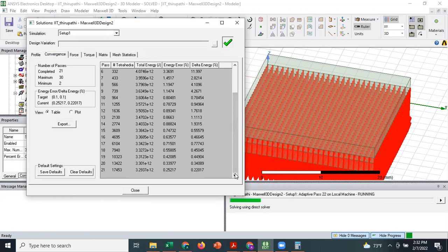Here you might have noticed that we have not given any mesh operation. So it is automatically meshing. This is one of the best features that Ansys Maxwell offers in static solvers, basically for the magnetostatic solver, and also the electric solver and the eddy current solver. It is applicable there, but for the transient solver and the AC condition it is not applicable. DC condition I'm not sure about, but for the other solvers it is not applicable anyway. We have to manually mesh for that.